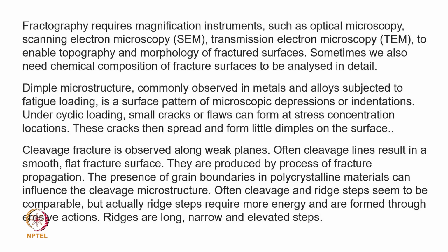So, in a way, fractography requires magnification instruments such as optical microscopy, SEM, and TEM, that is, transmission electron microscopy, to enable study of the topography and morphology of fracture surfaces. Sometimes we also need the chemical composition of the fracture surface to understand whether there is any oxygen or any chemical reaction or some other phenomena happening along with the wear phenomena. So, we really require those kinds of instrumentation for fractography. Now, we have shown something like a dimple in the slide.